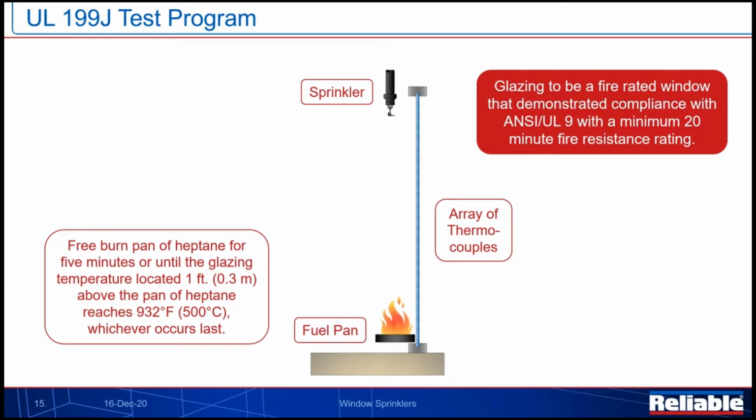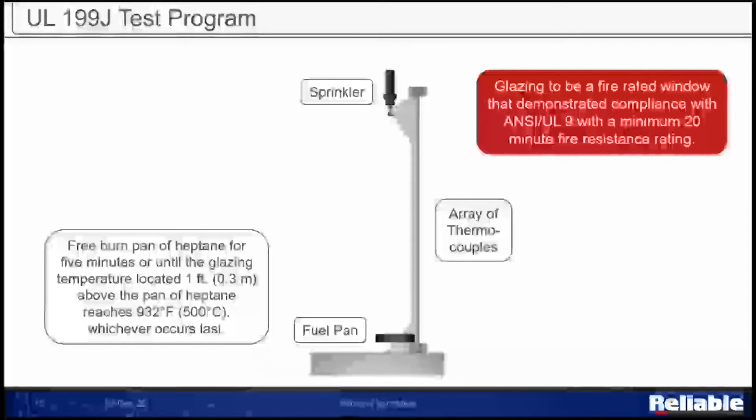But ultimately, we're putting so much heat and temperature into the glazing material that when we introduce water, it's going to shock it thermally, and typically this would break regular glazing materials. But what we're doing is we're offering that 20-minute product, and we're sort of supercharging it to make it go up to 2 hours. It's a very interesting way of combining sprinklers and upgraded fire-rated materials to get the end result of 2 hours. So just a different type of test.